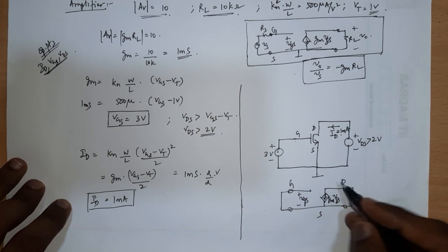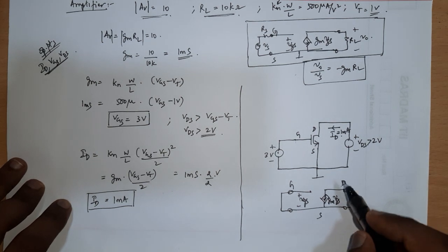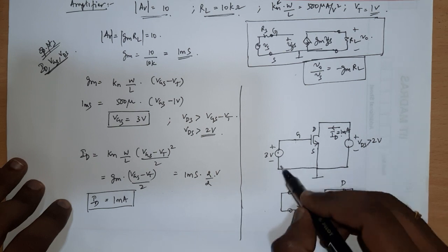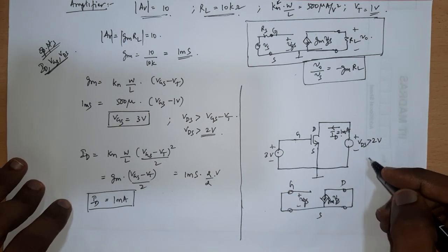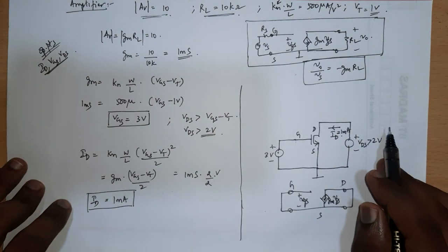What would I do? Nothing. VGS equal to 0, no current will flow, no output, right? So I cannot just connect things like this. Just connecting a DC only will not help me amplify anything. I should also connect AC signals. So how do I do it?